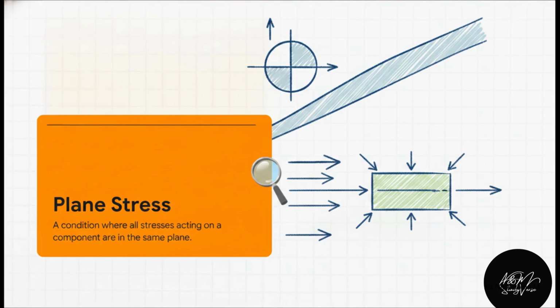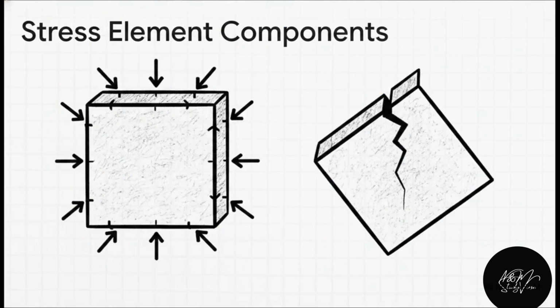To understand how Mohr actually mapped this stress, we need to take a magnifying glass and zoom way down from a giant hill to a tiny microscopic square of soil. We do this by assuming plane stress. It's a handy simplification where an incredibly thin element has all its stresses acting in one single plane. Making this assumption lets us analyze internal forces using a simple 2D stress element that represents just one single point inside the ground.